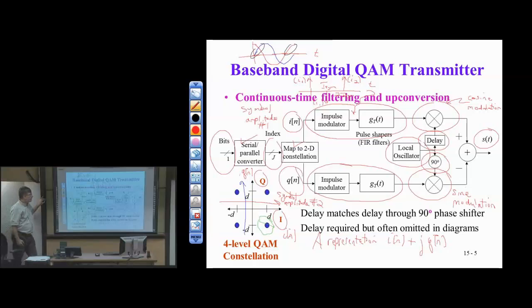Okay, so one of the cool things here is that I'm getting 2 PAM signals in the same transmission bandwidth as I would have gotten 1 PAM signal. Remember, there's an efficiency factor that we lose if we just did upconverted PAM. I end up doubling the bandwidth of the message signal when I upconvert. Seems wasteful. So the good news, again, we saw this back in homework 3, is that I can put a second PAM signal into the same transmission bandwidth without, at least on the transmitter side, the two interfering with each other. As long as I can keep the two modulation signals 90 degrees out of phase, then I keep them separated and independent of each other.